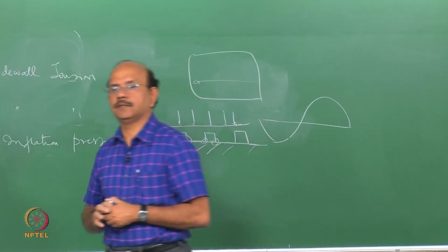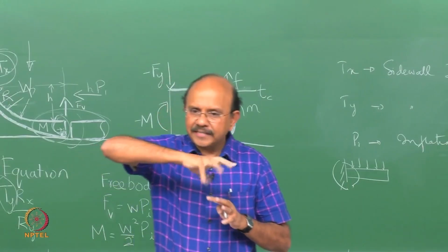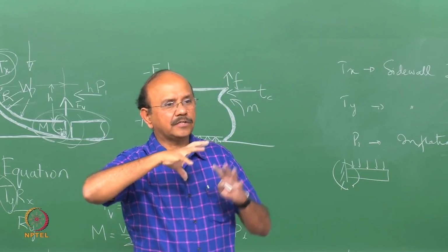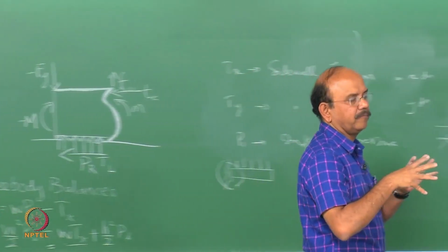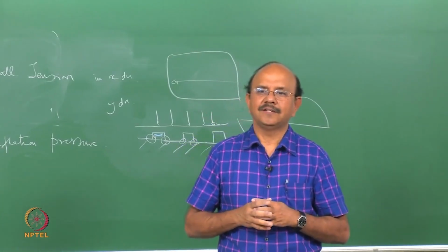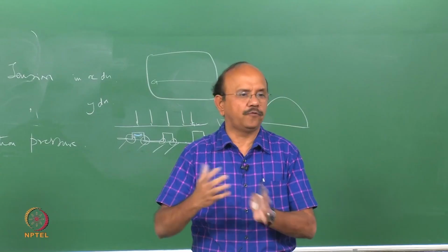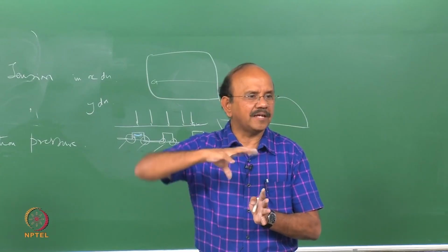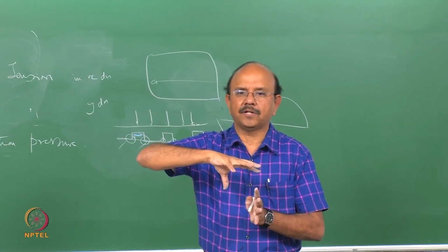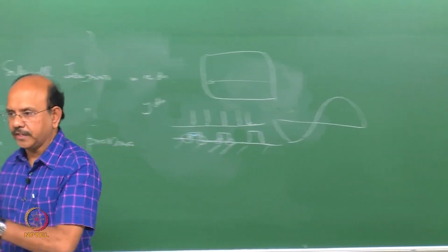Because of which, the tire now rotates a bit about the vertical direction so that the total strain energy becomes minimum. So in other words, this uneven distribution of forces causes the tire to adjust, or in other words, the contact pressure now is such that the total strain energy is minimum.